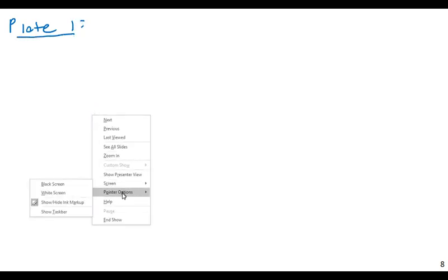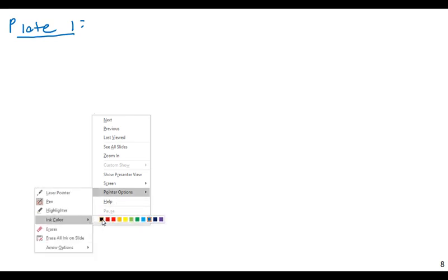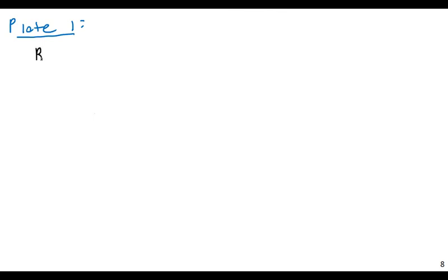For plate 1, the first step, of course, will be to calculate the Reynolds number. The Reynolds number is going to be equal to Vx divided by nu. Now, another note here. Always use fluid velocity? Well, let me think about this.